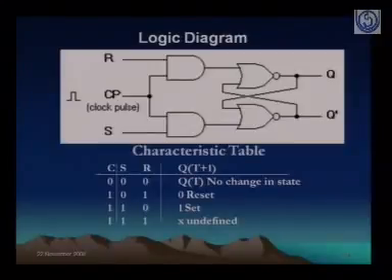Similarly, for the reset case, even if the value of R moves to 0, the flip-flop remained in the reset state. So that is what it means: no change in state, right? If it is 0 and 0, there is no change in state. Whether the clock occurs or does not occur does not matter in that case, so it can be 0 or 1.